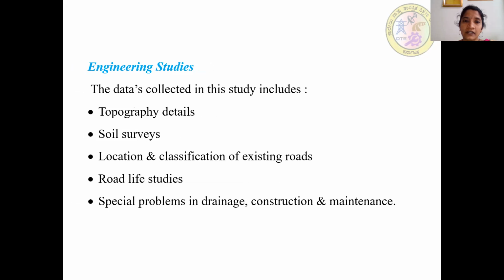Next, engineering studies. The data collected in this study includes topographic details, soil surveys, location and classification of existing roads, road life studies, special problems in drainage, construction and maintenance.